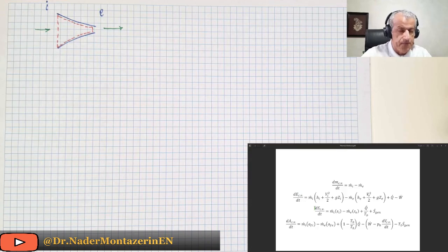Usually, at least in the thermodynamics lectures, we study steady flow, or we integrate between some initial and final condition. For the present problem, we study steady flow, so therefore all left-hand sides would be 0. The change in elevation is negligible for a nozzle.